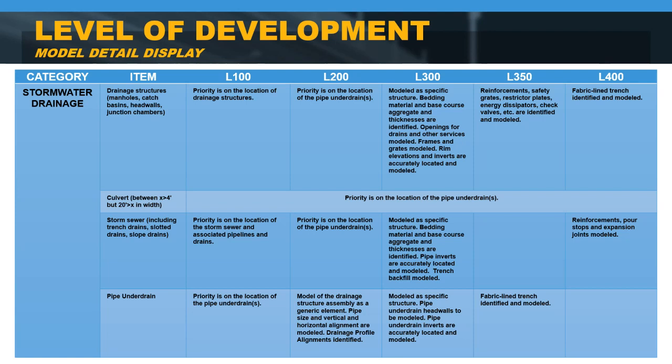From here, we knew we needed to establish better standards and began working on an LOD table. Over the past year, we have coordinated heavily with our partners at IDOT in order to establish some consistency amongst the agencies, which often utilize many of the same consultants. We plan to release the LOD table within the next week for agency review. So shown here is a snip of what we've put together. And one aspect we pride ourselves on is that the developed table is going down to each element to capture detail on and describe it from the L100 all the way to the L500. We have also developed templates for different types of projects to help for scoping purposes.